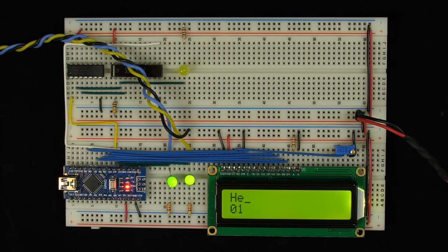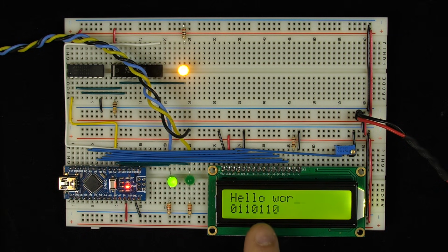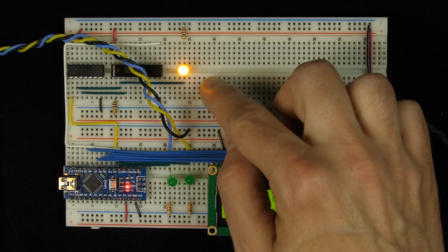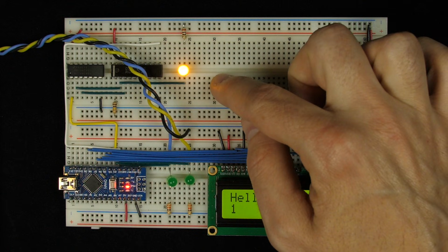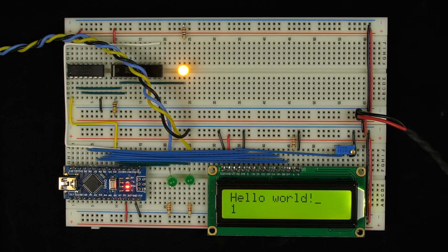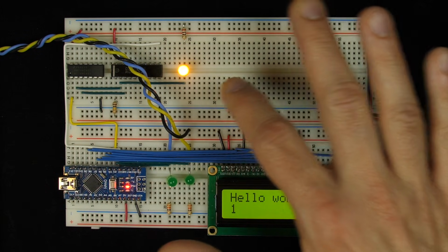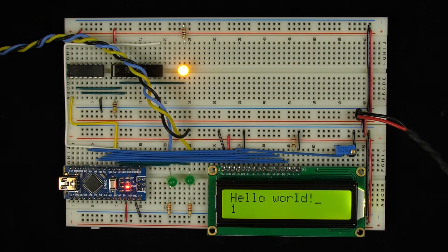So let's take a look at the receiver again as we receive a message. Now again, we've got this message where we received hello world without a comma. So was that a mistake or not? Well, because this LED is on, we know we received an odd number of 1s. But now we also know that our transmitter has even parity. So counting the parity bit, the transmitter will always transmit an even number of 1s. And so anytime we receive an odd number of 1s like this, and this LED is on after we're receiving, we know that there must have been an error. Because the only way we could possibly receive an odd number of 1s is if some bit got changed along the way after it left the transmitter, either a bit in our message or the parity bit itself.